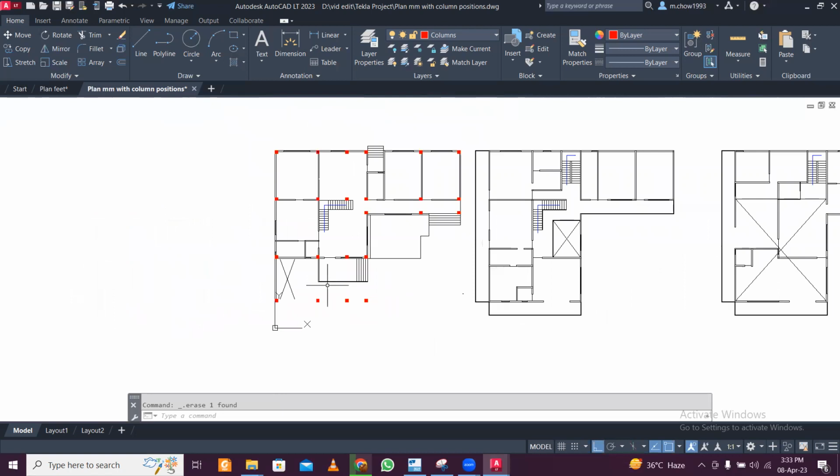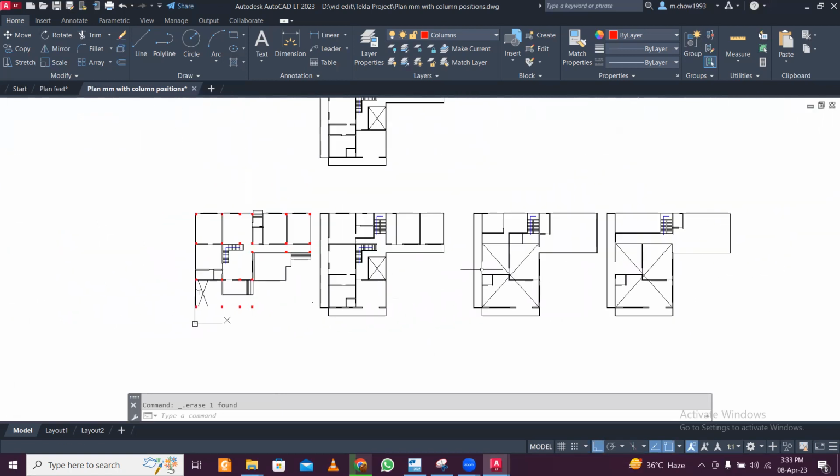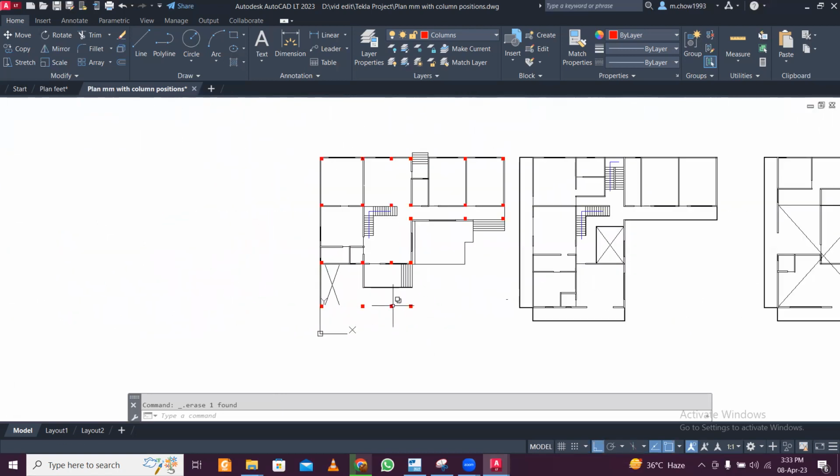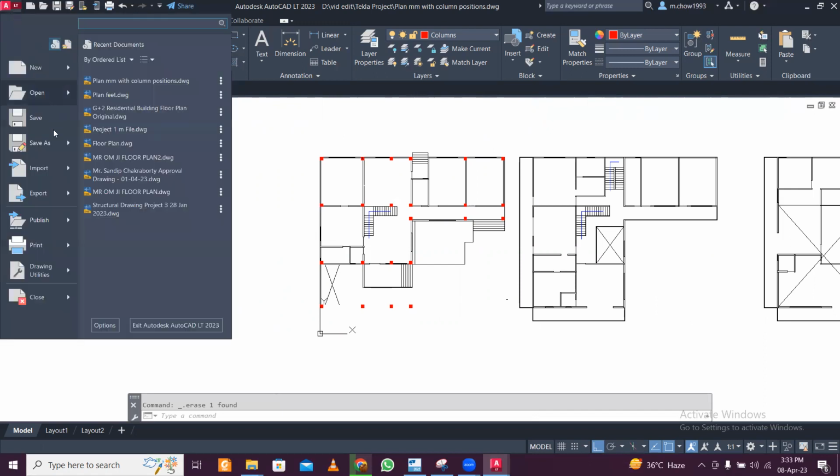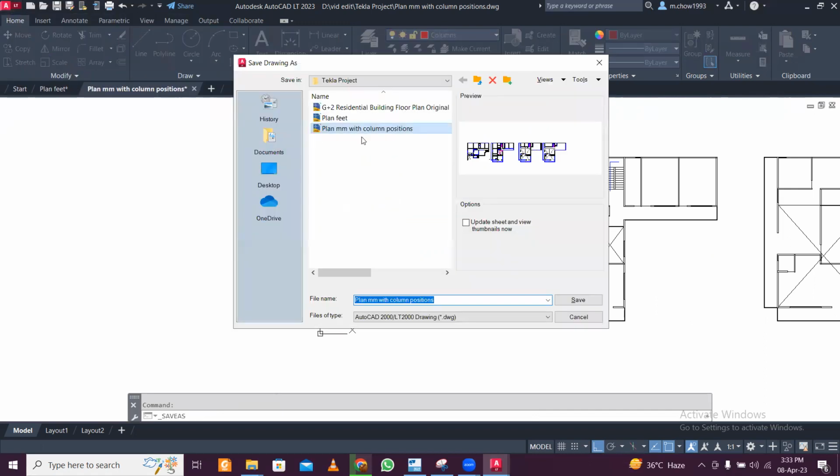Later I'll also show you, if possible, how to do the remaining things as well. Okay, so making the center line for this, let's proceed forward. I just want to make the center line for the ground floor first. I'm going to right click and save as center line for ground floor or 10th level PL. Okay, so I'm going to save this.